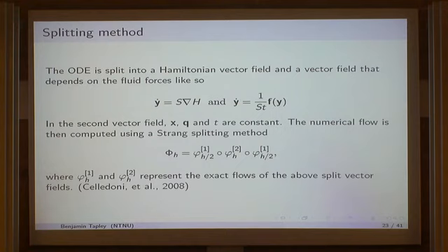Yeah, we're just going to use the Strang splitting, where these two operators denote the exact rigid body solutions and the variation of parameters formula. Again, we're going to compare this to what's typically used in the industry, which is an Adams-Bashforth method. And one of the reasons why they use that is because you only evaluate the vector field at integer multiples of the time step. And in these numerical solutions to the Navier-Stokes equations, we only have this vector field at integer multiples of the time step.